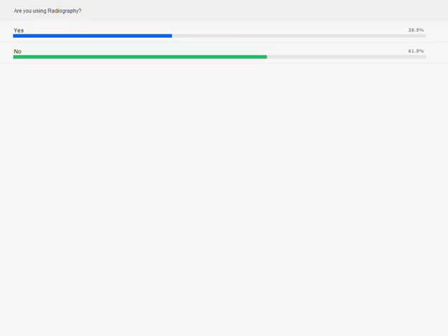Sure. I know we have a very diverse audience with us today, so for some of you there might not be a need to use radiography, or some of you might not be using any NDT at all. But especially for pipelines, there is still quite a big amount of radiography being done out there. In most cases, for pipeline construction, there are not too many limitations to replace it with ultrasound. What we find is people generally don't want to do it because radiography is what they know. The people that need to see the images are used to the images. And there is a process under most codes, under ASME, API, and the other regulating bodies, that if the code says historically we use radiography, we must go through a certain process and show that ultrasound can be performed in lieu of radiography. That also means new procedures and new training when we change techniques. So there's still a lot of work, but we see this number going up each day.